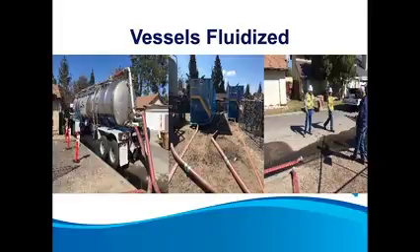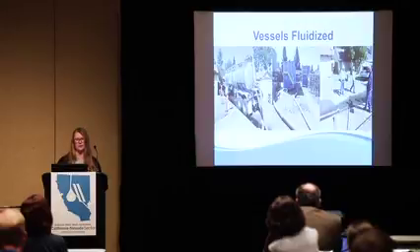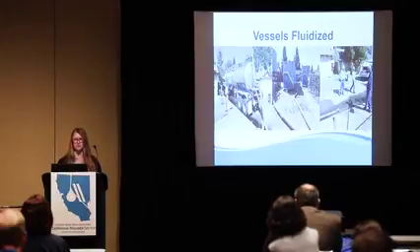Here are just a few pictures of how we fluidize the vessels. You can see the unit there on the left is the Calgon. Our vendor Calgon has designed a special bed for us that has a sacrificial carbon compartment in it, so when we're washing the fines, we don't have any problems with our discharge permits. It's something we do on all of our GAC changeouts, as well as first fill on our GAC.